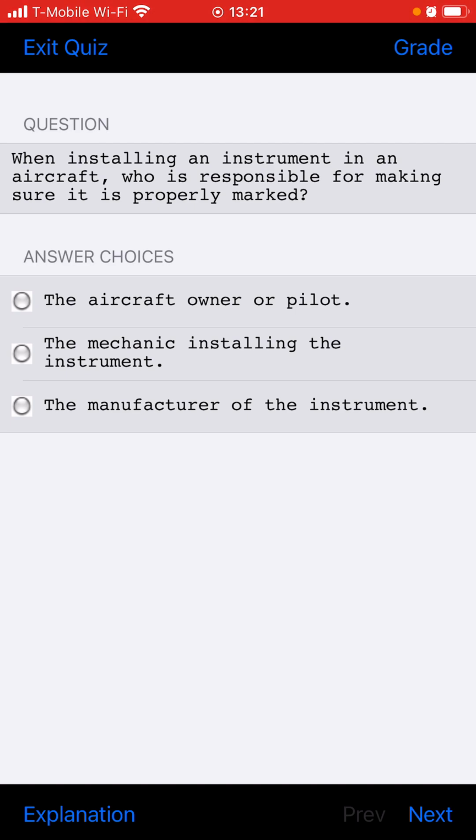After a component in the pitot-static system has been replaced, what tests or inspections are required? The static system leak test specified by FAR 91.411.